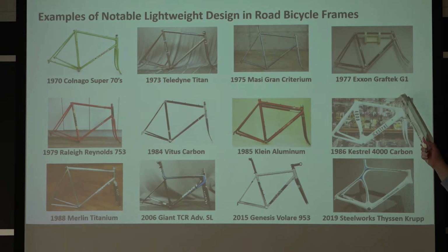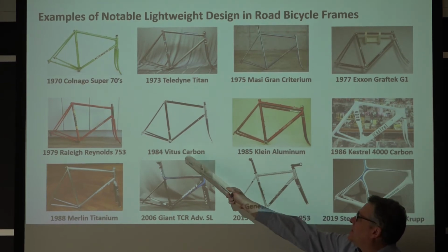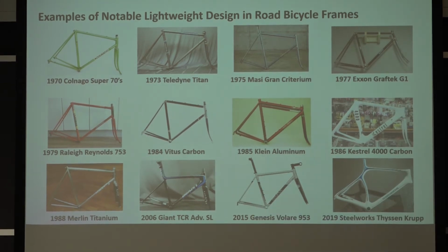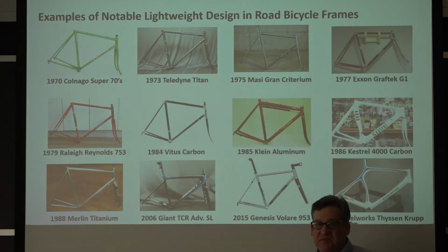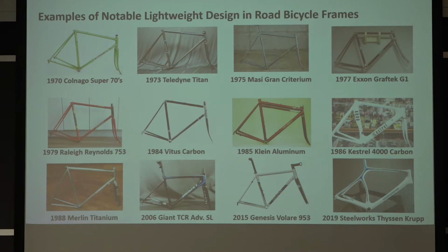Carbon fiber actually came in the late 70s, believe it or not. They used a cast aluminum lug, and then they used structural adhesive to bond on a pre-made tube. That tube might have been made through braiding, for example, or another process. Vitus made this technology popular in the mid-'80s. The problem is they didn't quite have the structural adhesive figured out. They didn't quite know how to do structural adhesive properly, and these frames inevitably failed by the joints ungluing or debonding.